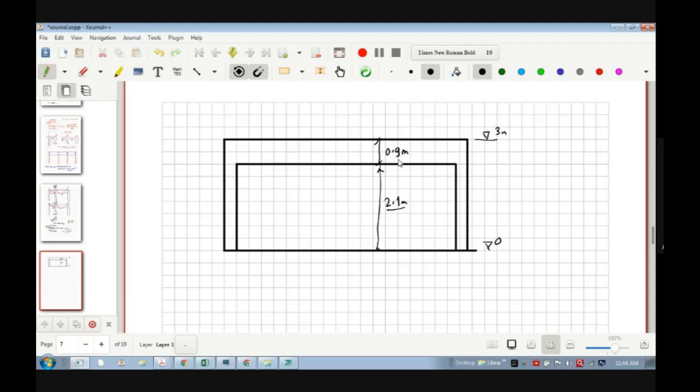So this depth will not be acceptable. So it will have a real issue to the architect. Architect, you can talk to architect, either allow me one column in between, or I need this depth only. So what can you do? So many times what happens, actually this is not the case in school buildings. We generally have a more floor to floor height because the spans are more. It is generally 3.6. Okay, 12 feet roughly. It may be 12 feet.